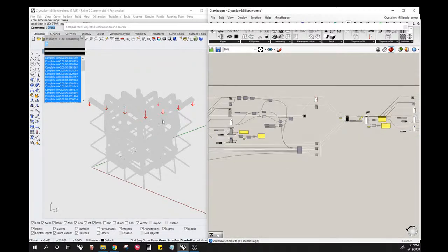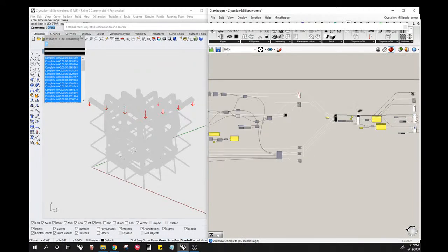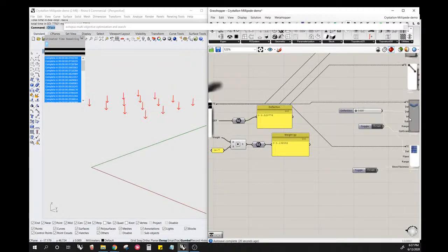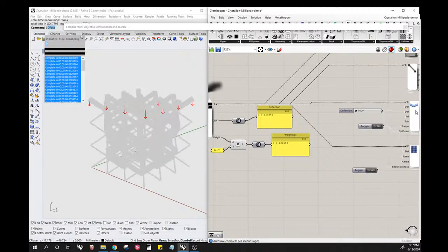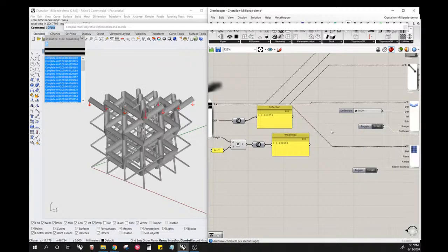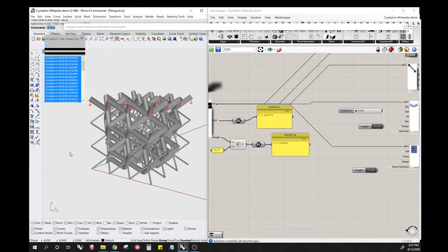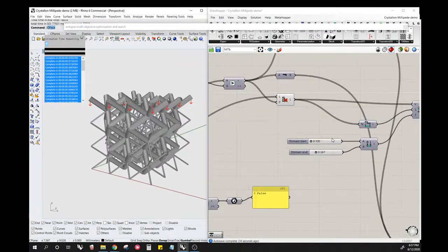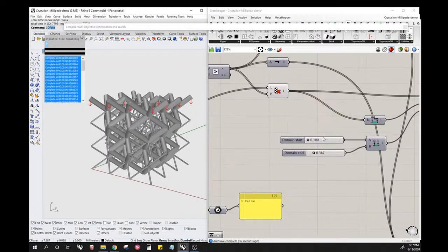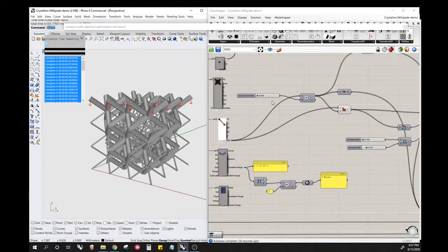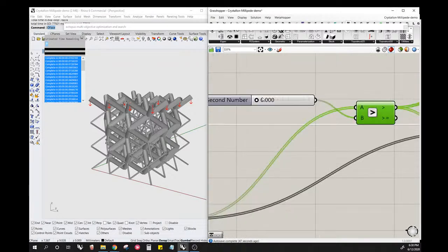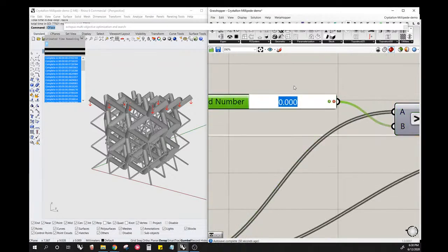Another thing we can do is preview these so we can see the beams a little better. I'll look at none so we can see these a little better. These little beams, right now they're at 0.1 millimeters or something like that. So we might not even be able to 3D print these, and they might not be necessary at all. So what we can do is filter those least important beams out of the simulation. And what I'll usually do is filter out, say, the bottom 10%.